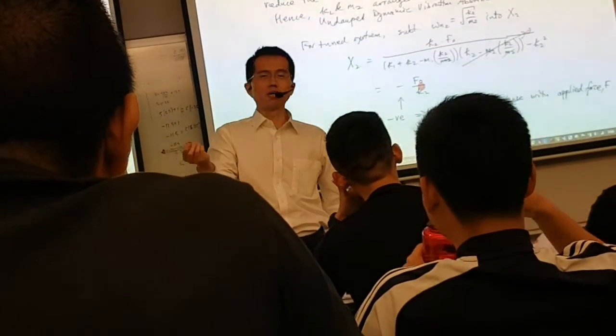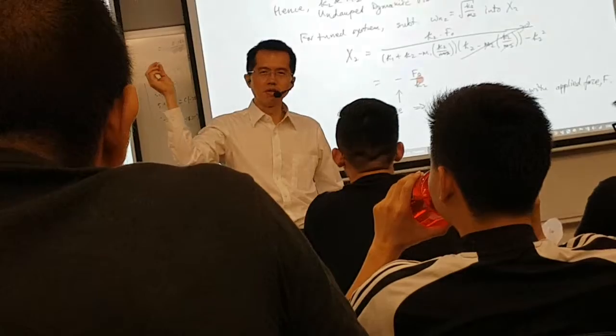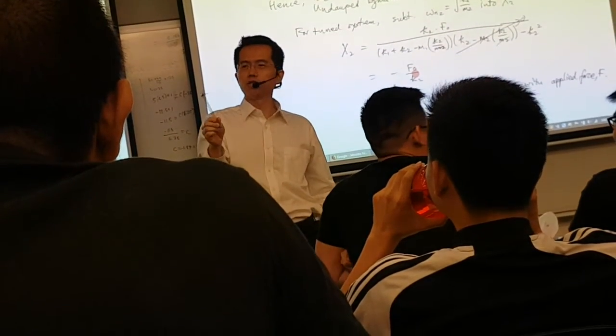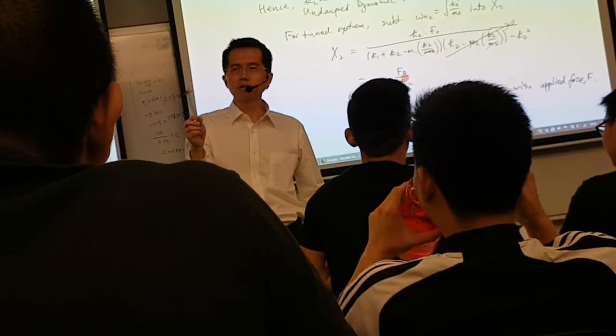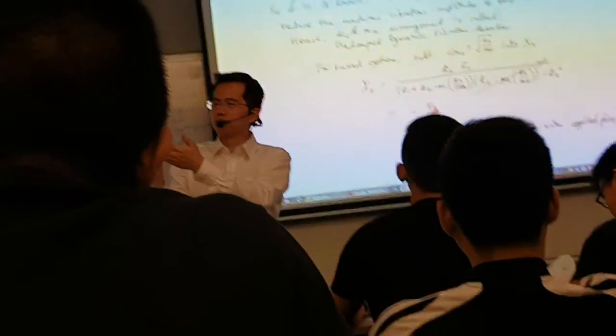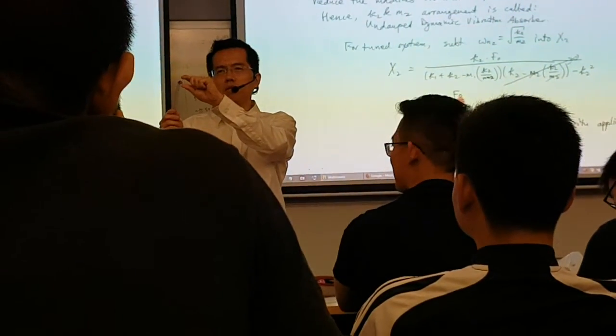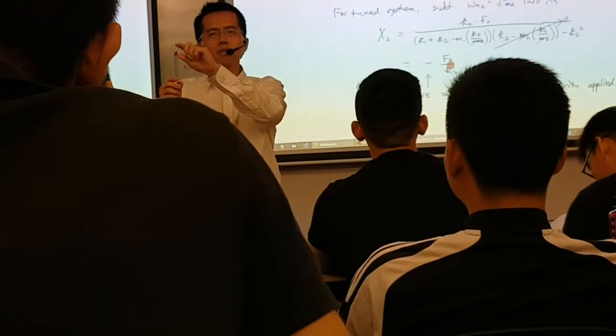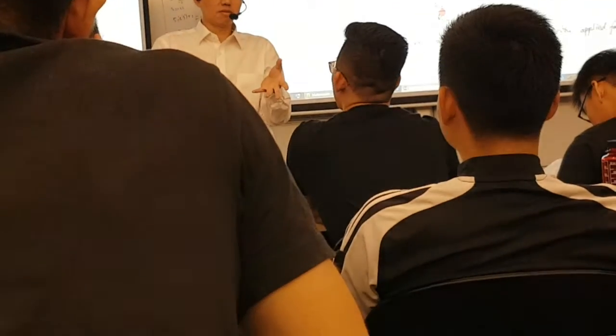This is very useful, very powerful. It's an additional mass on a spring attached, but you need to design it. This is an absorber. You need to design what the spring constant and the mass are in combination. Then it will absorb that resonance energy into here, and this will start to resonate. So that's the concept.